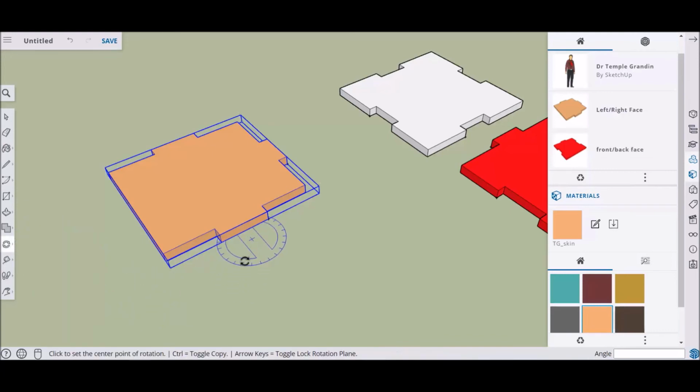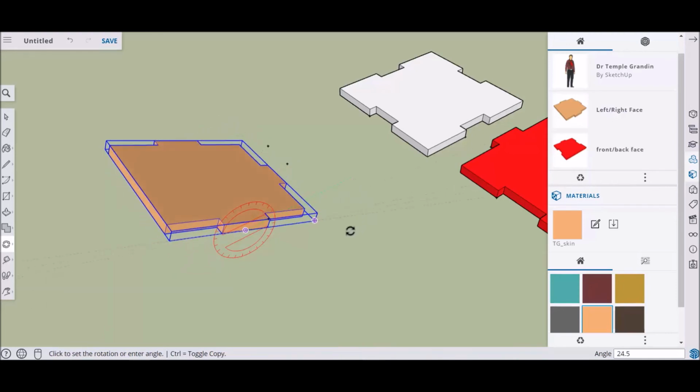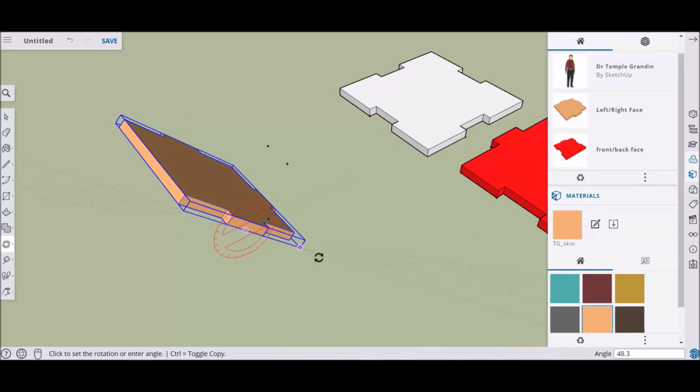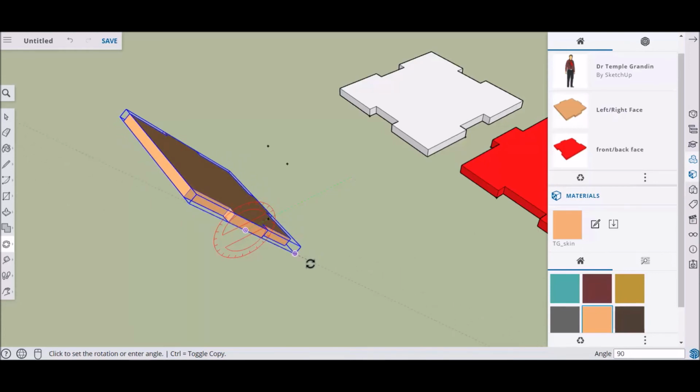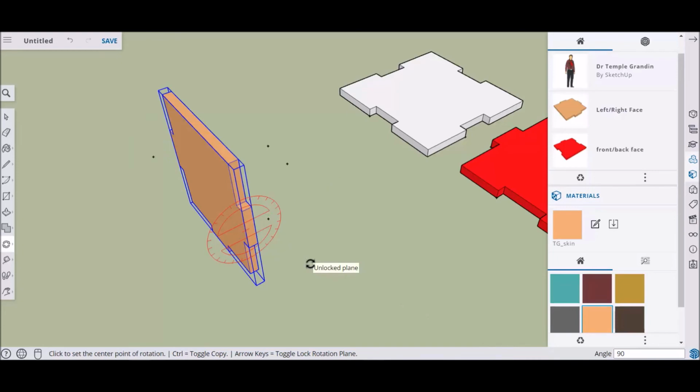And I want it to rotate from that end to come up. So if I pick this side face, I'll pick the midpoint of there, click, and then it gives you a line. Just click somewhere else, and you can start to drag it around. You see at the bottom where the measurements are now, I've got angle, so I can just type 90, press enter, and it'll put it up for me perfectly at 90.